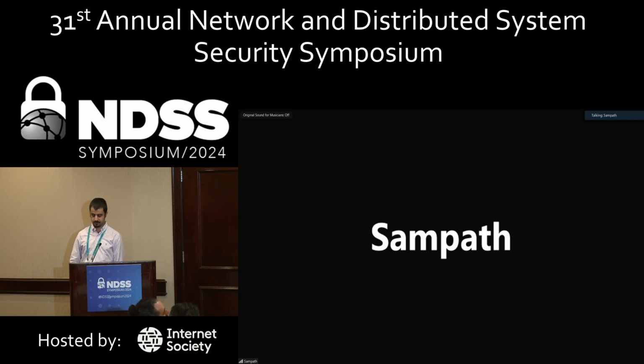Yeah, basically, we generated our own attacks. We got partial access to the DBC file, and we also observed some of the payload data using a CAN sniffer. Then, based on that, we created our own attacks. The attack types are some popular attacks, like sniffing, spoofing and replay attacks, but based on the CAN data specification, we created our own attacks.